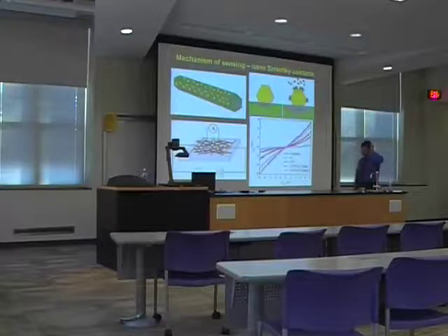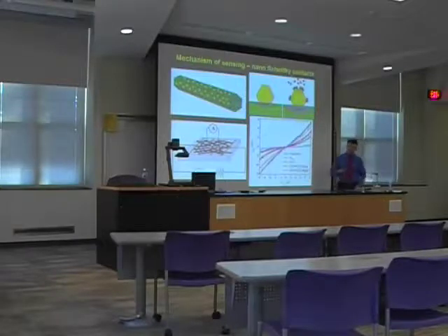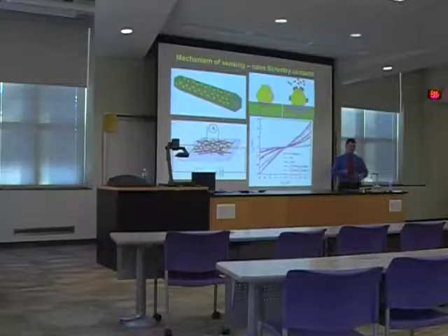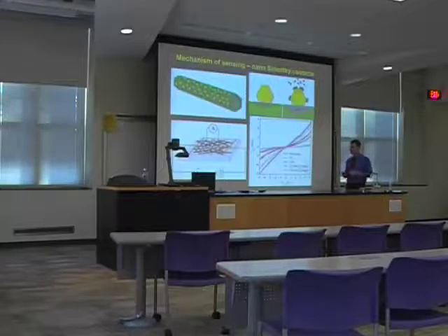But the most important thing is that this is kind of digital sensing. When I say digital sensing, I mean that this is the way to detect presence, not quantity. Because if you inject even a little bit of hydrogen or a little bit of CO, you reach saturation almost instantly. So adding CO won't change this drop in conductivity.